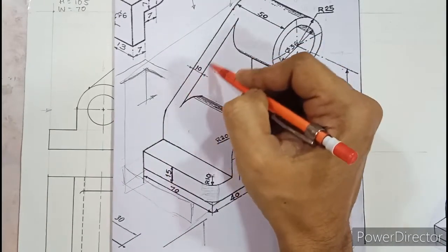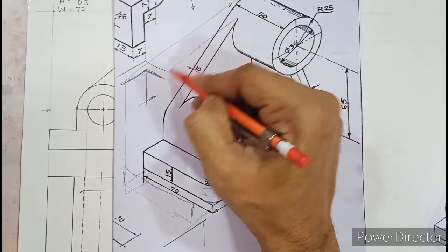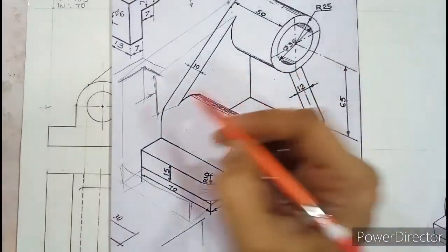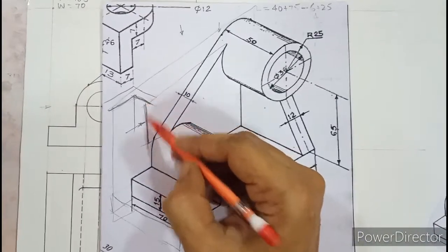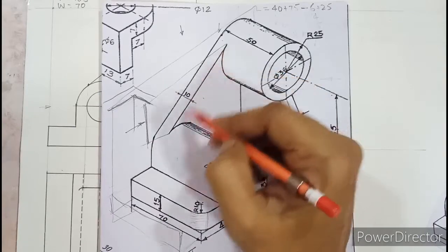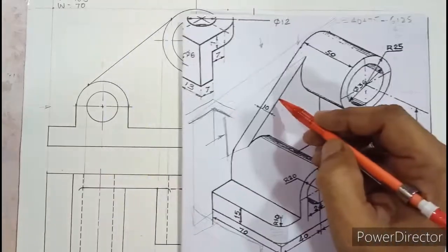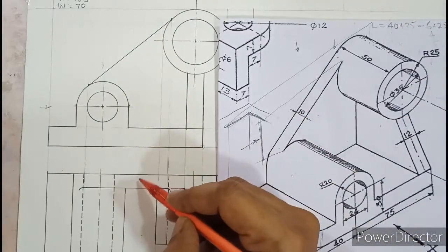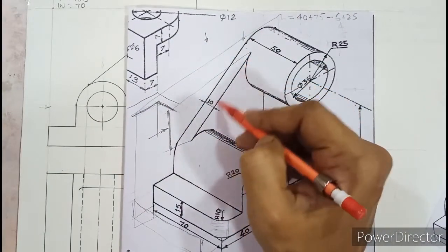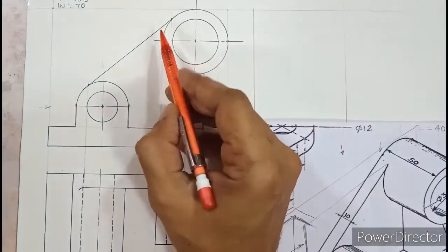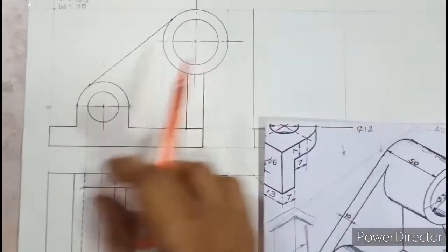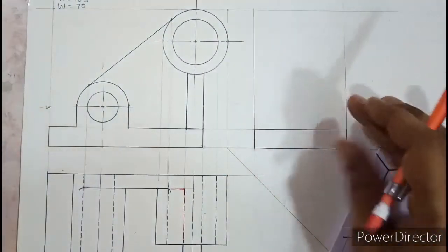So the next edge, if you look in the side view, it is seen as a vertical line. But what about its height? How much it is? So the height of this edge must be equal to the gap between the merging points. And the width is 10. So width 10 millimeter is same as this width in the top view. But if you look at the height of this rib, you'll get from the front view. So where it is? In the front view, we have marked two merging points. So if I can project this here and width 10 mm from here, I will get the merging rib.